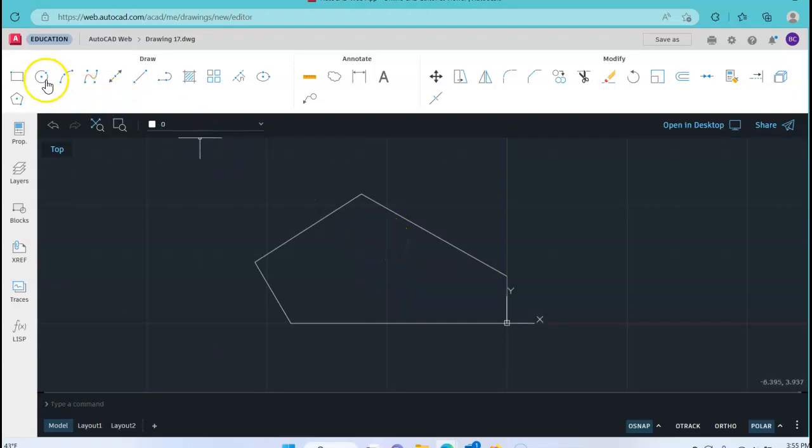And when I go to my circle tool command, again, I need to know what those coordinate points are. Well, I'm given those off of my 0, 0. So this very first one over here, the x coordinate is going to be -1. I'll put a comma. My y coordinate is 0.5. Now, I'm getting that directly off the print.